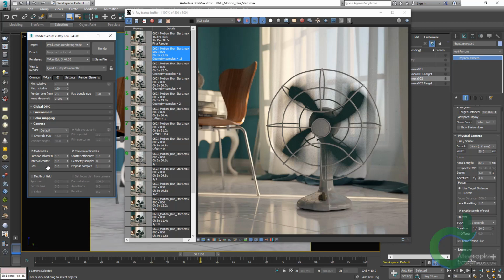Bias controls the bias of the motion blur effect. A value of 0 means that the light passes uniformly during the whole motion blur interval. Positive values mean that light is concentrated towards the end of the interval, while negative values concentrate light towards the beginning. These options are really not that important and you really don't need to change them.